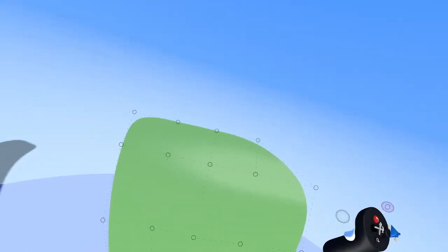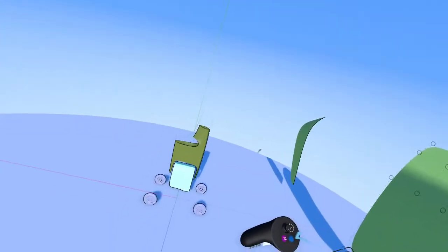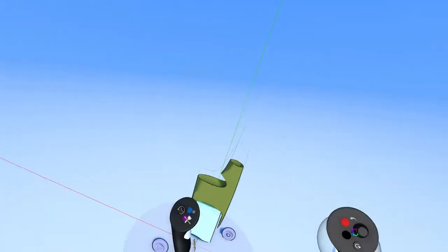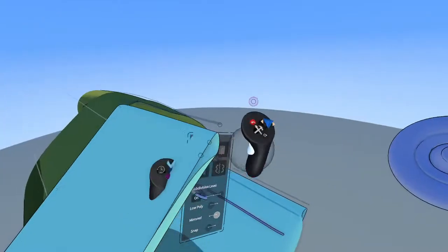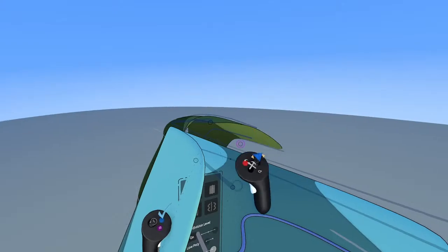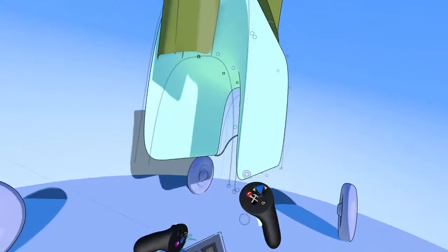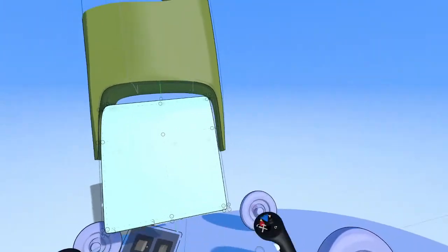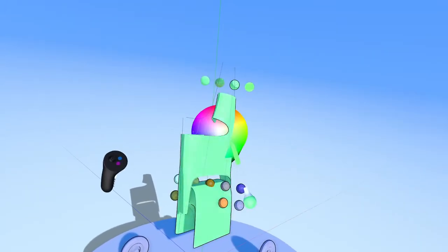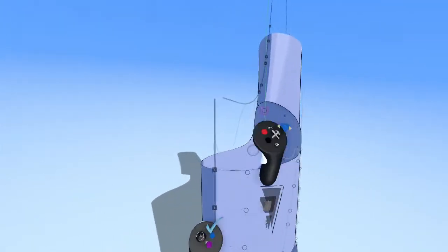Now triangles are not ideal. They're not what you're shooting for, but you have the flexibility to, in a compromised situation down here, make a triangle. So that's what I'm going to do here. I'm going to click that like that, duplicate out an edge, pop it in right there, and delete that extra edit point. And it's not that big of a deal. The shape is still connected together. It still looks decent. All right, let's try and pick up the speed here a little bit.